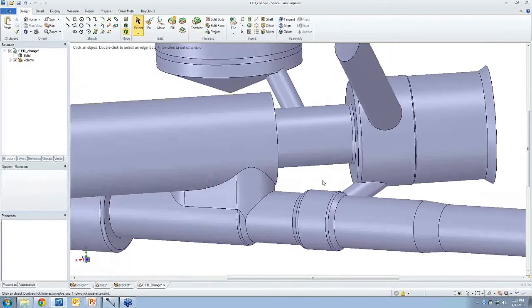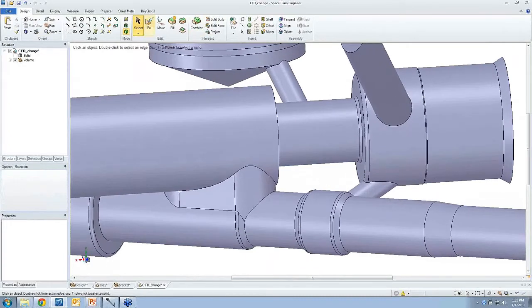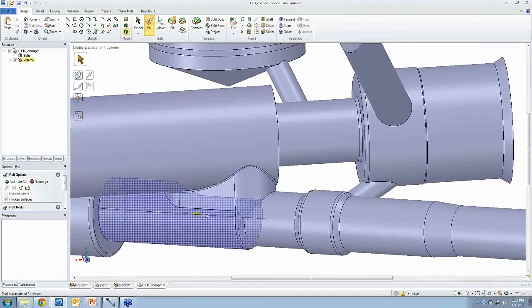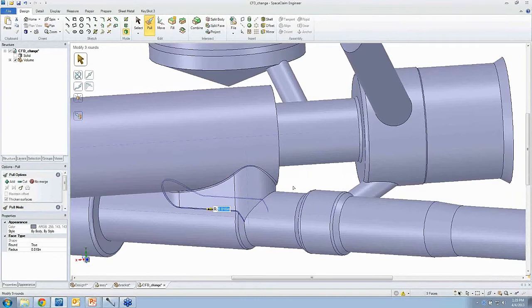If this isn't what you want, you can always run through a different iteration. And obviously this is going to have some rounds along the perimeter. Smooth things out. We'll call it 0.010 of an inch, something small. Try that bottom one again.